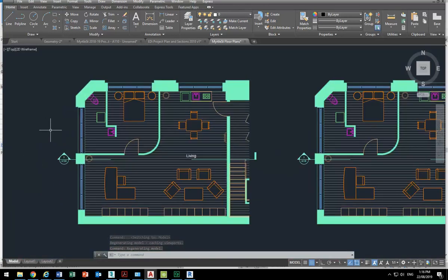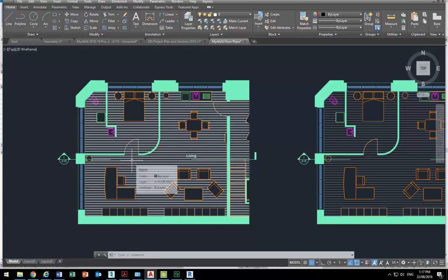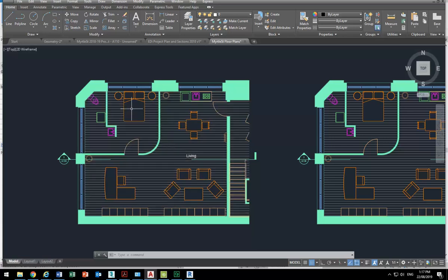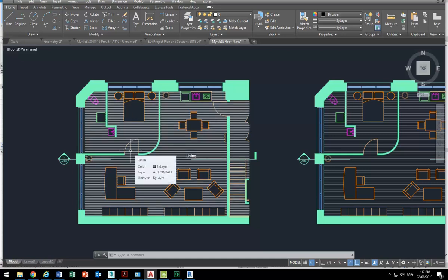things that are 3D in Revit converted to 2D in AutoCAD. And again, you can explode any of those things. So let's say you want to change the bed. Now, later we should look at changing the furniture, but for now it's a preliminary plan, so we can leave the furniture there. But later you'll have to take the furniture off. Is that not part of the construction? That's right. Construction drawings don't need furniture unless it's built in.